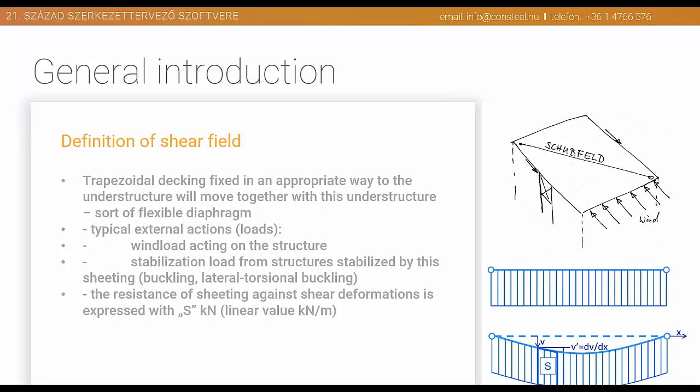Now, if I don't disregard the roof panel, and just consider it in my design, even in a safe way with a reduced amount of rigidity, it would give additional stiffness to the frame, the period of vibration would decrease, and the seismic force, calculated through a modal response spectrum analysis or even in a simplified way, would be bigger because of the smaller period of vibration.